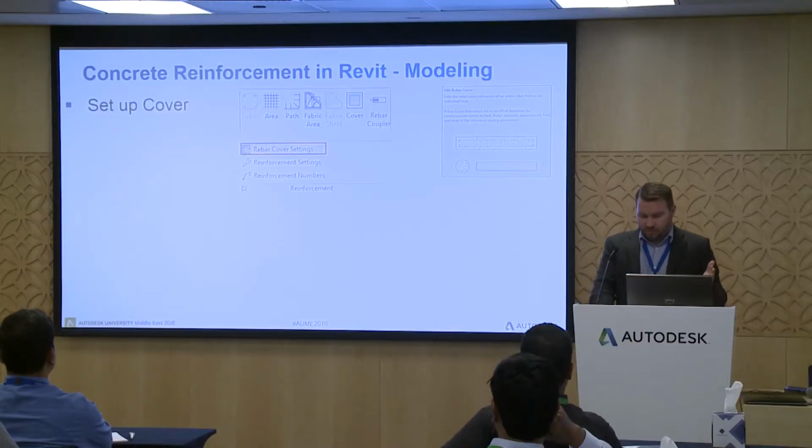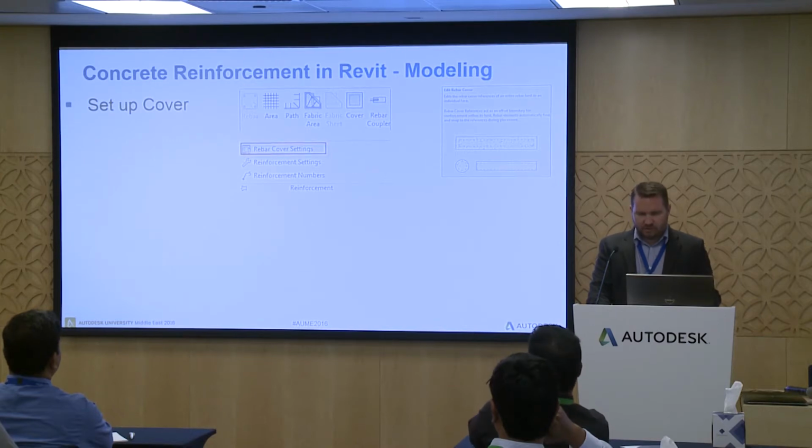shape to put a little picture in it, so you have the display at the end of the final drawing. By default, all the elements have a cover. So first you will set your rebar cover settings.